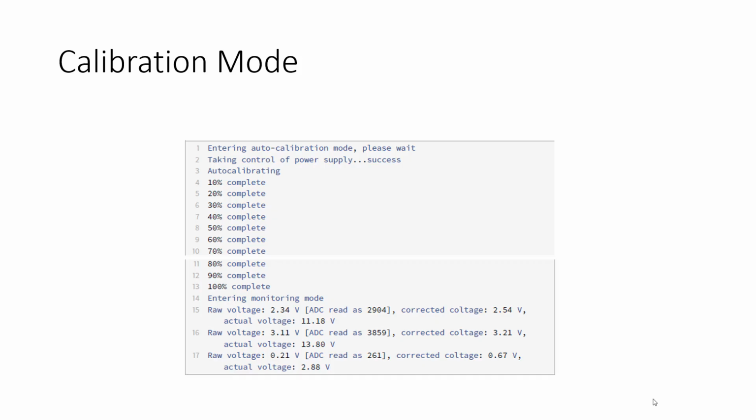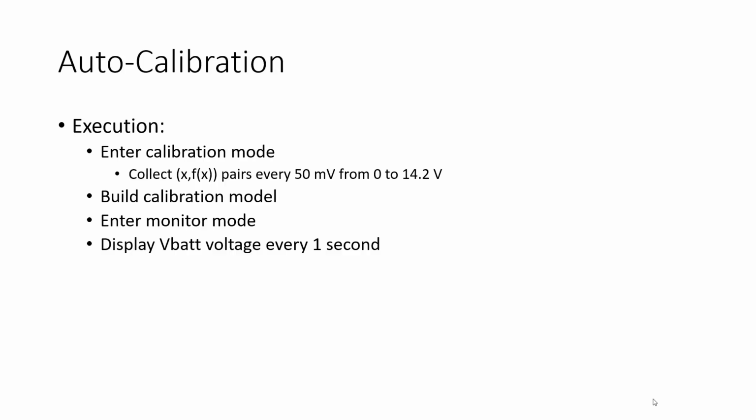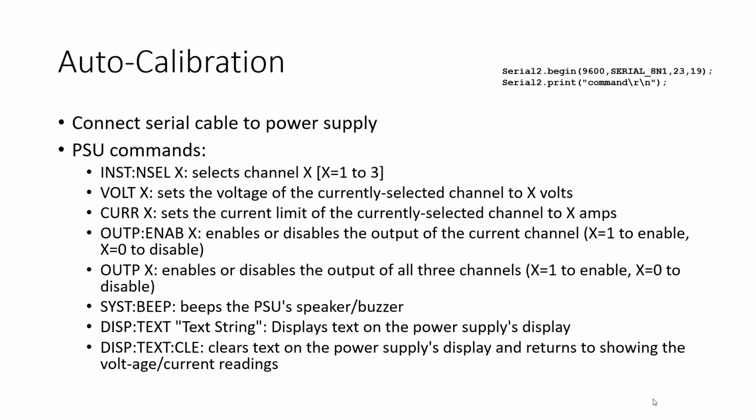So you get to control the power supply. You get to connect the power supply to the board and then use the ADC. Okay, so how do you talk to the power supply? Did I use the whole time up? I did almost, sorry. Okay, power supply. As I mentioned, the power supply uses essentially English words that you send it over an ASCII text interface over UART.